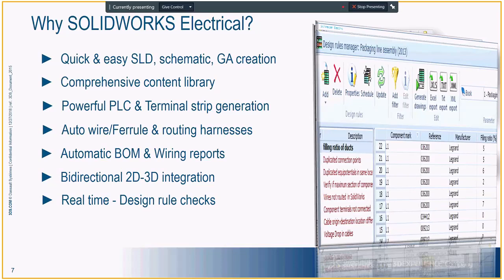If we have 100 components added onto the schematic page, we can check how many of those 100 components have manufacturing parts associated with them. Likewise, different templates and design rules define and identify errors related to the project, reducing the time of the quality engineer.